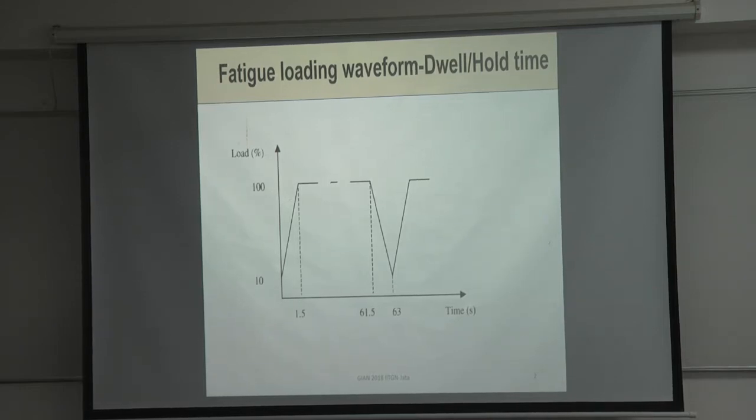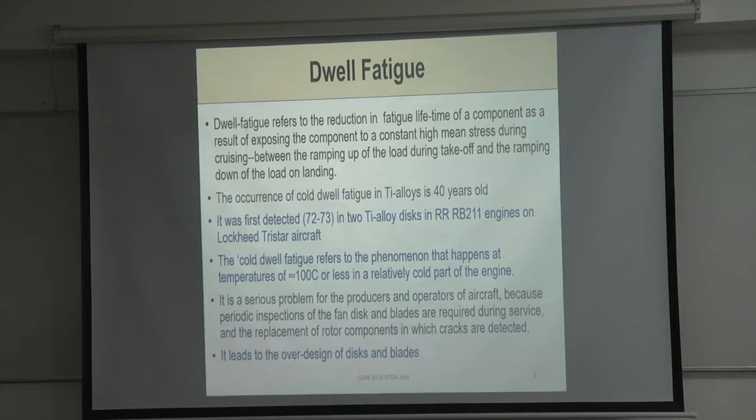I made some remarks here: what is dwell fatigue? It refers to the reduction in fatigue life. You know that there is a fatigue life by regular cycles, but when you put in that hold time, you find that the fatigue life of a component goes down, as a result of exposing the component to a constant high mean stress during cruising, between ramping up and taking off and landing.